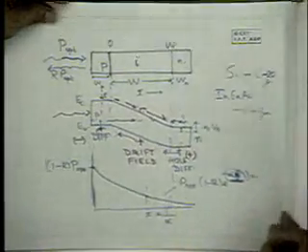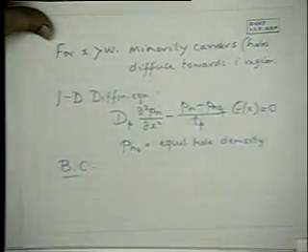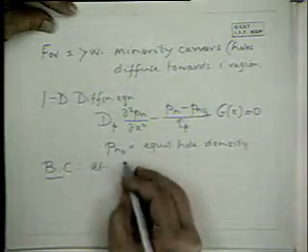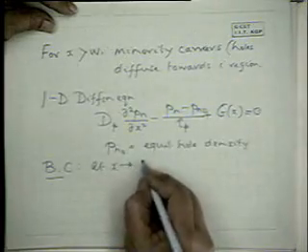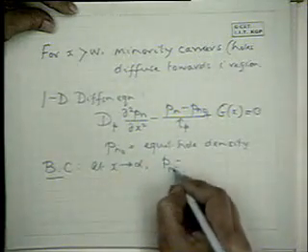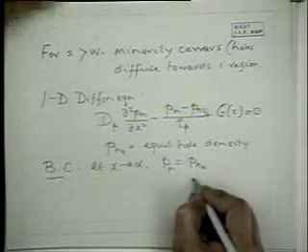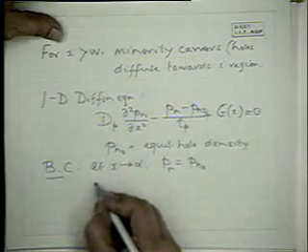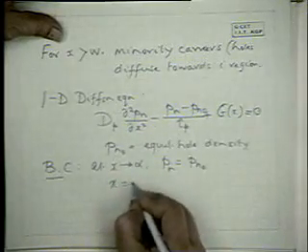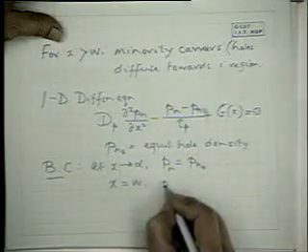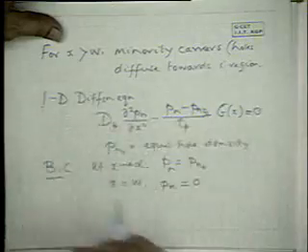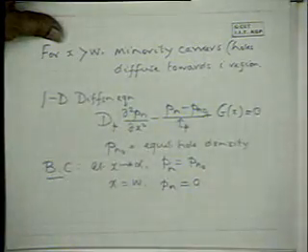So the boundary condition is that at x equal to infinity, Pn is just equal to Pn0, because there is no light penetrating towards the end of the device, and at x equal to W, Pn is equal to 0, because the holes then diffuse into the I region.